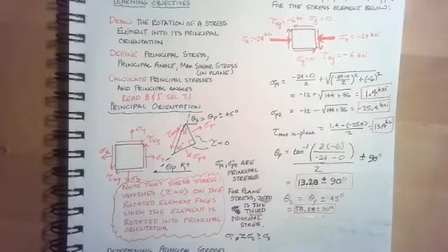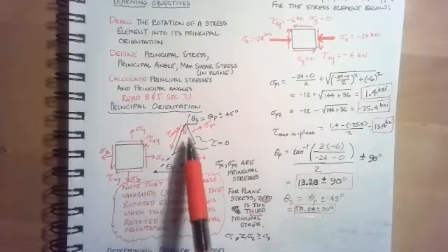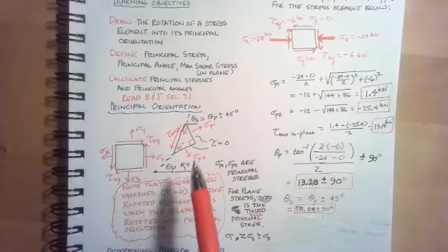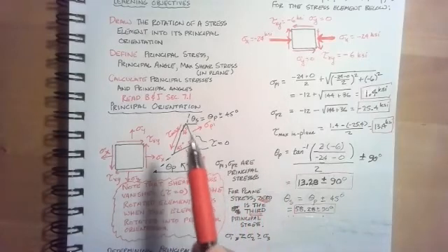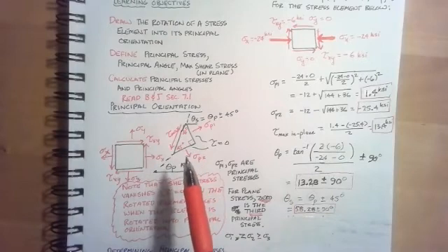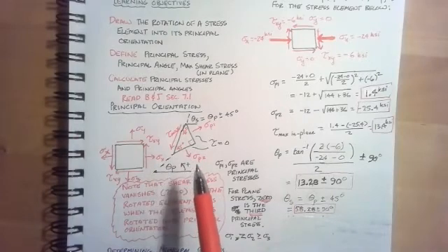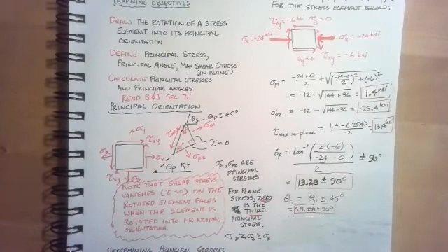By principal stresses, we mean the stresses on this element of material that I would get by rotating this element into an orientation where the shear stresses would go away.